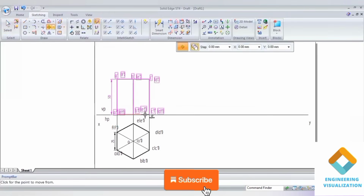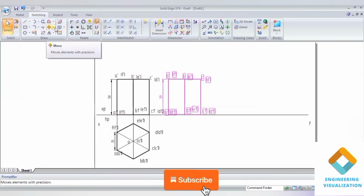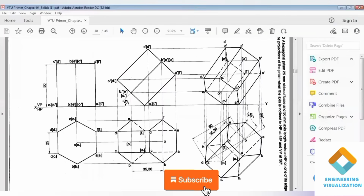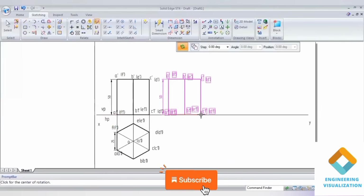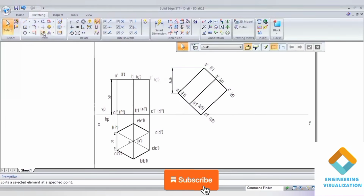So use the move command, create a copy, slide along the xy line and go to rotate and take the base edge inclination. It is 45 degree, so incline 45, so it has been inclined.